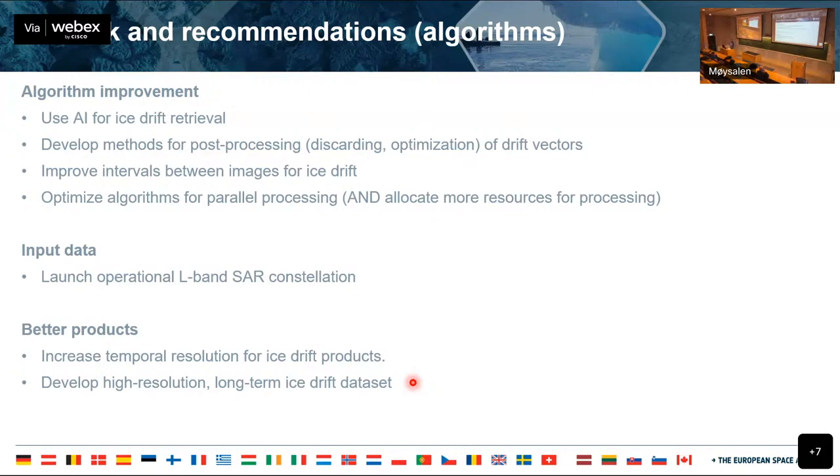I would say that speaking of synergy is to combine a SAR deformation with ICESat, CryoSat related sea ice thickness estimations, because the SAR gives you the short-term deformation, which then you can use, and openings and closings, basically to verify the thickness distribution and the contribution of deformation to thickness and volume change, which is derived from the altimetric products.